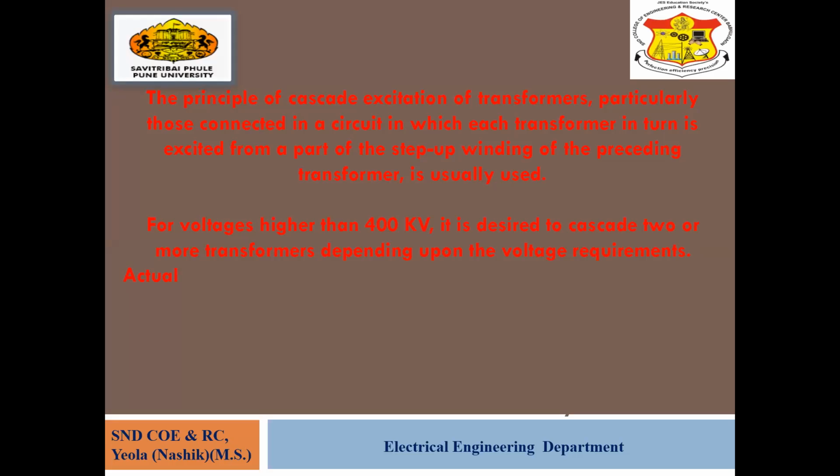What is the principle of the cascading transformer? The principle of cascaded excitation of a transformer is that each transformer in turn is excited from a part of the step up winding of the preceding transformer. I have told you that the output of the preceding transformer is given as an input to the successive or next transformer. So the principle is the same: the output of one transformer is given as the input to the next. For a voltage higher than 400 kV, it is desired to cascade two or more transformers